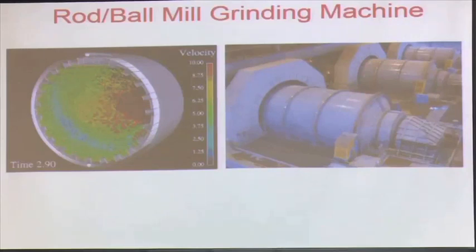Why? Because that water helps in many ways. One is basically transport of material, how the material will be transported, suppose from this end to this end. It also helps in segregating my particles, because when you are breaking the particles, there may be a chance of further agglomeration because of incipient fusion between the particle surfaces.